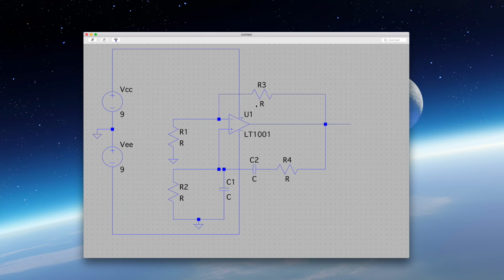So as I said before, this one will be my feedback resistor for the inverting input. And this one I intended to do 30K here. Just 30K will be just fine there. And this one I intended to be 10K. So 30 over 10 is 3. Okay.